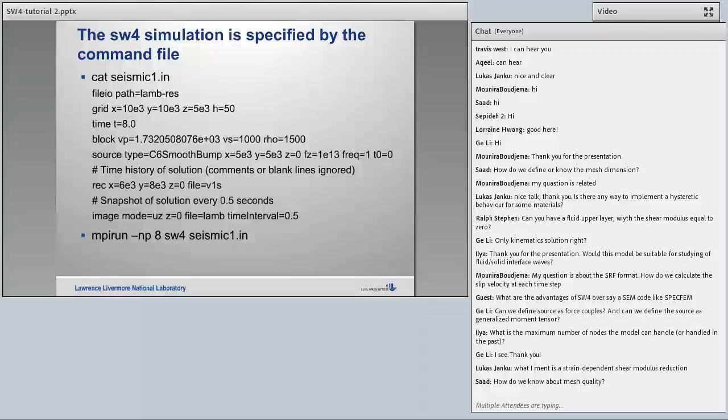Okay, so then there's a new question about mesh quality. The quality of the curvilinear mesh, in general, will be improved if you make the curvilinear mesh thicker. And it's going to be more and more Cartesian, because there's going to be less and less stretching.